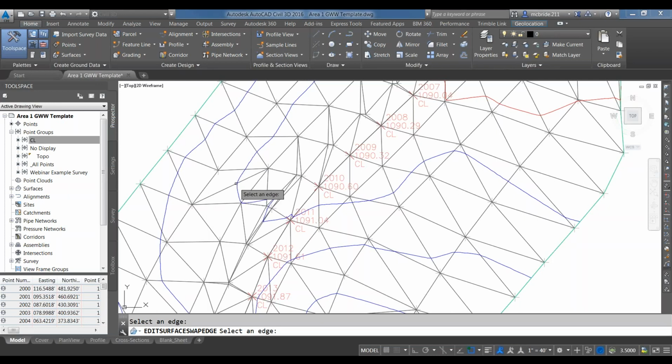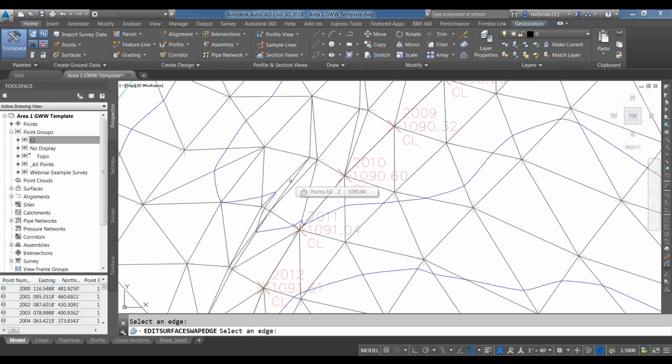Now it didn't change it much here because this is a fairly well represented square that, based on the elevation data, it's not going to change the contour lines too much. However, you get into some issues up here where you get a lot of these gray triangle lines that are very close together, and then you start producing some of these weird jagged lines, and those are what we'd like to get rid of. So there's no real step-by-step method to this. You just start clicking lines, and you can see it just changed that a little bit.